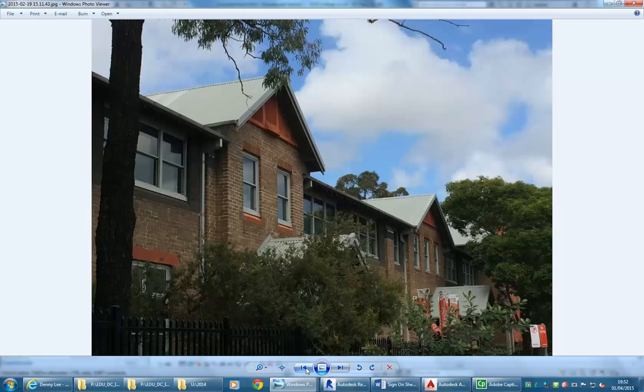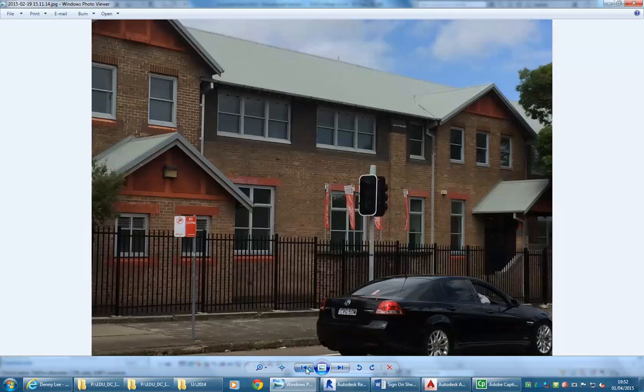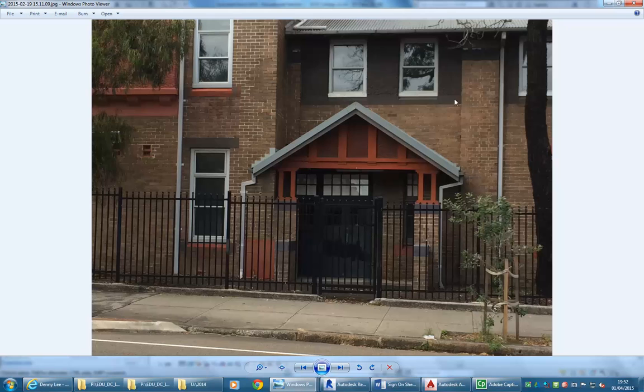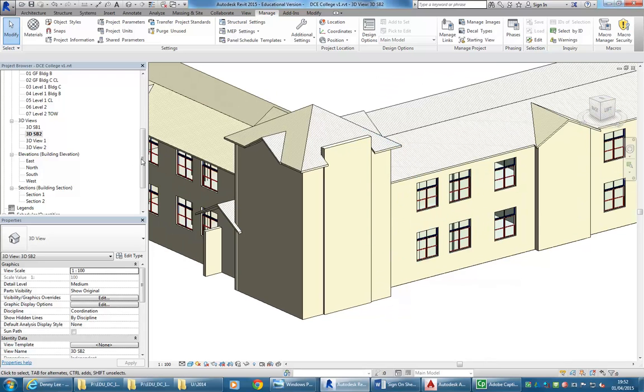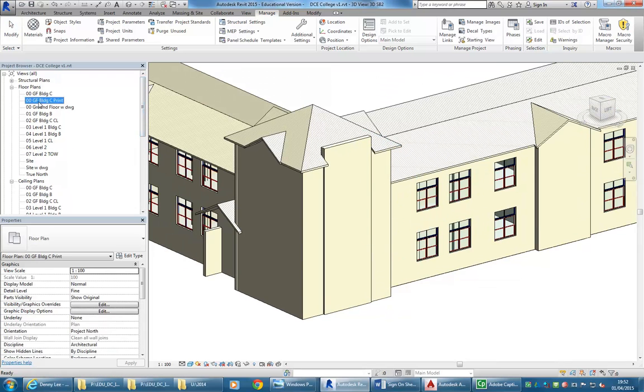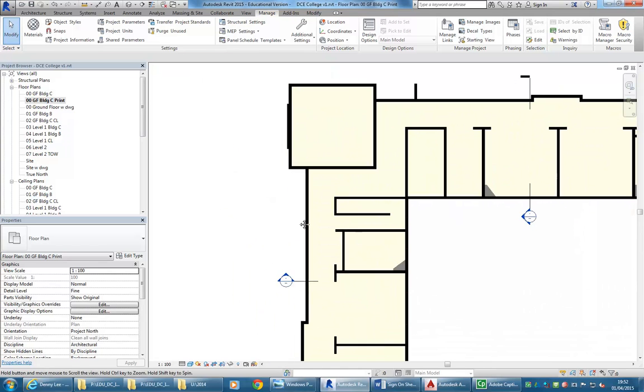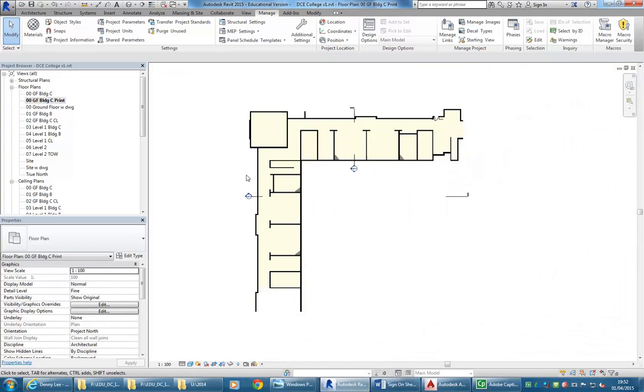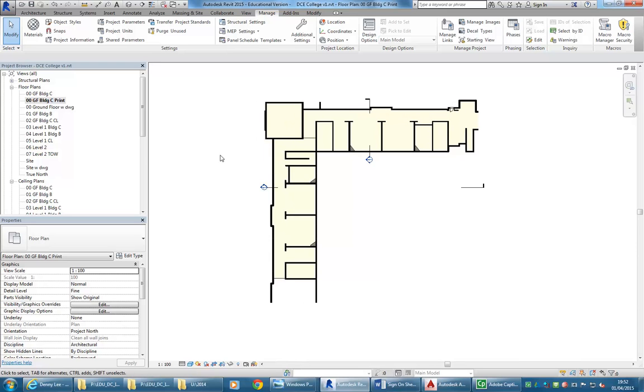Yeah, so that's something that you probably won't have on the floor plan, but if you can relate it to something, it's essentially in between the two, also to one side of the window bays. So going into my plan view, I want to work now with the windows, so a little extra thing I'll show you there is how to get the windows to show up in the view when you don't see them. This will happen quite a lot with a project like this, where you've got lots of little level changes, and so you won't always see different things that are at different heights.